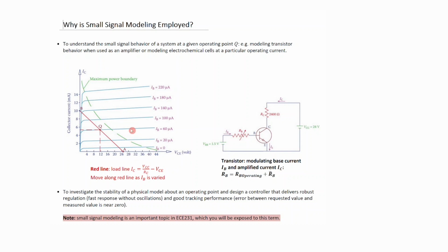Let's say we chose 60. Well, let's take 60, and let's say we go to 12. Collector-emitter voltage 12, that's the voltage across here, and that would correspond to approximately a collector current of 5 milliamps flowing into the collector node here, for a base current of 60 microamps. So these blue lines indicate making changes to the resistor and then seeing what those characteristic curves look like.